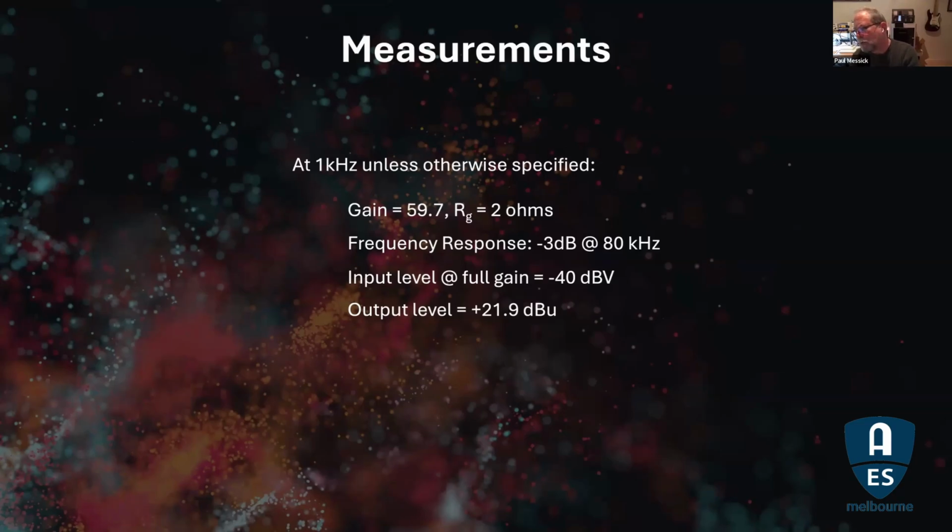A-weighting, we're sort of addicted to it because we get better numbers that way, but it isn't always particularly a good representation. In fact, sometimes you see adding an A-weighting filter and your noise goes up as you measure it. You see that quite often when you're dealing with extremely low noise, because there's actually a 1 dB gain at a kilohertz in the A-weighting filter. So that can actually make your noise look worse. But it's the same sort of idea.